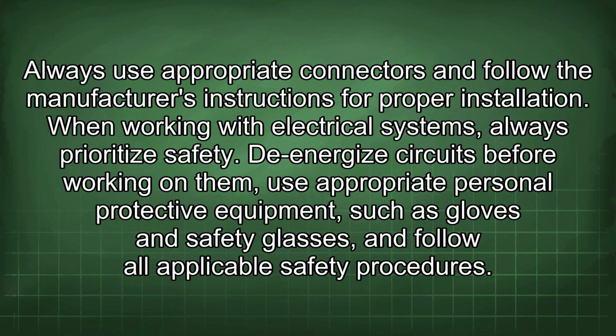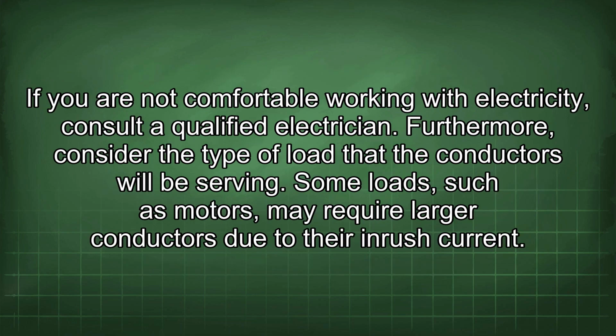When working with electrical systems, always prioritize safety. De-energize circuits before working on them. Use appropriate personal protective equipment such as gloves and safety glasses, and follow all applicable safety procedures. If you are not comfortable working with electricity, consult a qualified electrician.